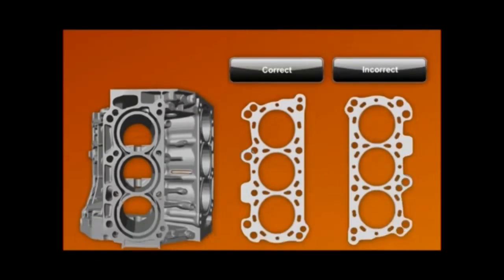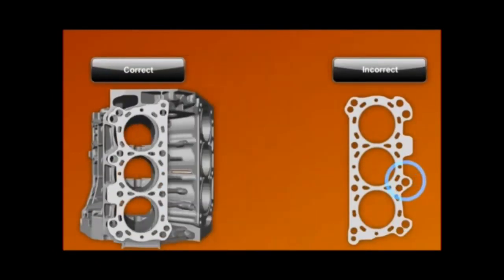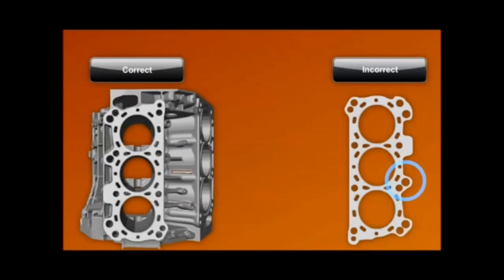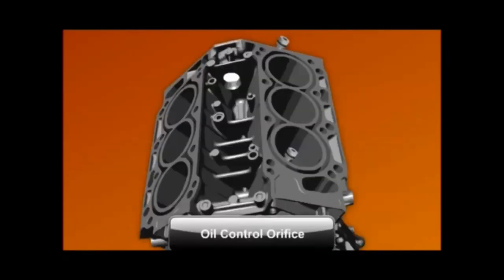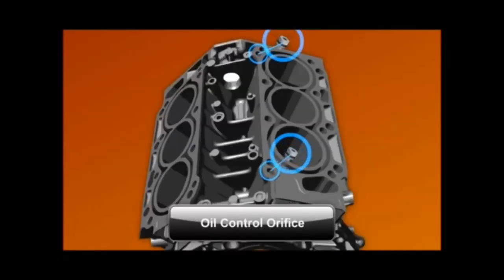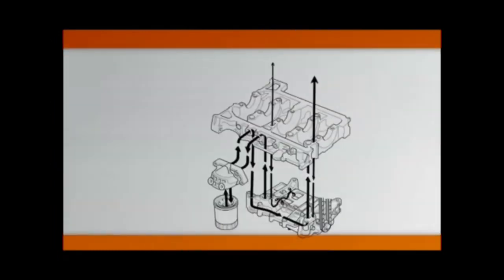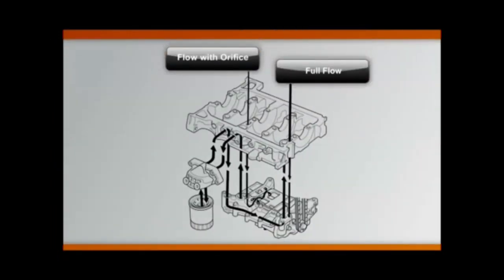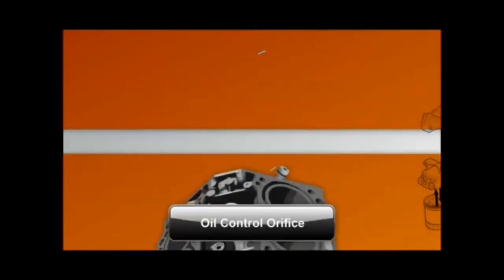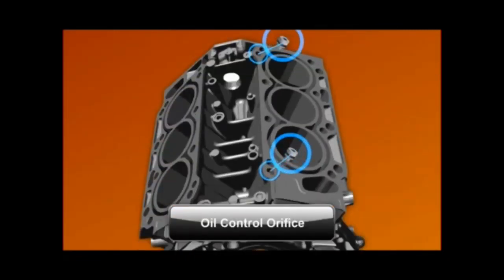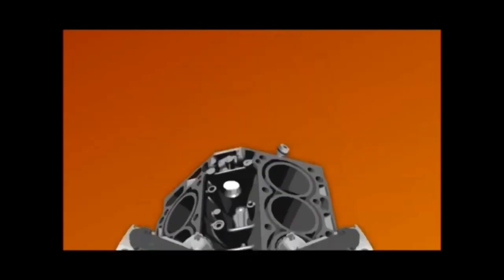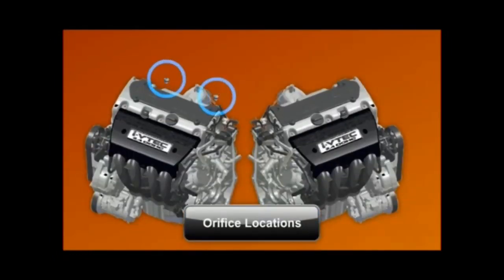From the oil filter, engine oil travels through oil passages. Manufacturers machine engine parts so that oil passages match up to components, so always consider oil passages when positioning gaskets during engine assembly. In some cases, an oil passage includes an oil control orifice. This device reduces oil flow. Whenever you disassemble an engine, keep track of the orifices. If you replace a block, be sure the new block has the correct oil control orifices, or transfer the oil orifices from the original block to the engine.